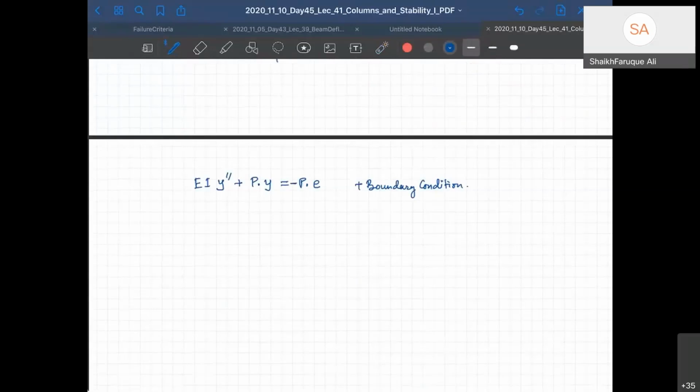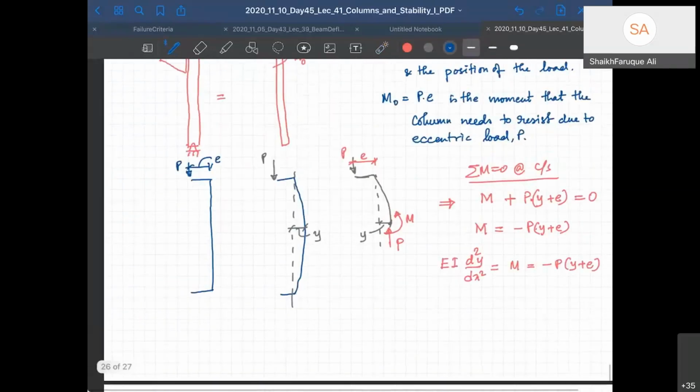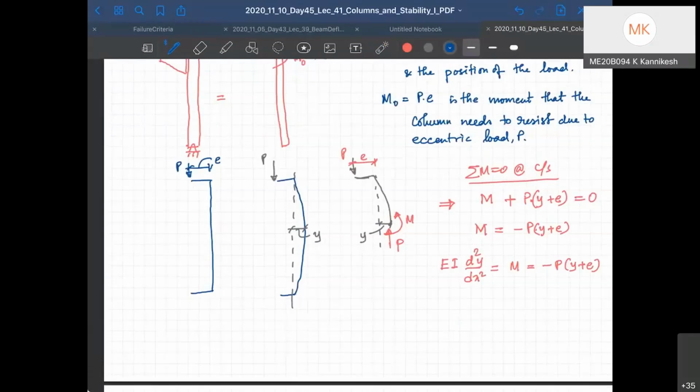Sir, I have a doubt in the previous slide. We wrote the moment at some x from the top. In that, shouldn't we first write the force? The force is on the rod due to the fixed surface, and then shouldn't we write the moment and shear force equation rather than just considering only the external force which is acting? Because of this force P, which is acting externally, the fixed surface will produce a force P and a moment, like which we wrote in the previous.